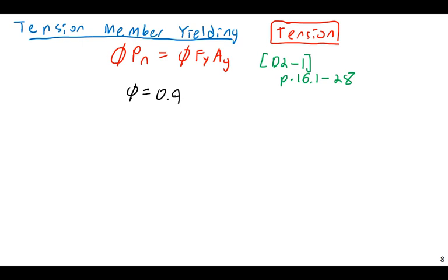It's meant to account for small but inevitable variances in the resistance that's actually present. Questions? Yes? Isn't that equation independent of the resistance factor, though? This equation here, yes, it's going to be independent of the resistance factor, although not necessarily, because at least here, phi Pn, yes, this part is, but this part isn't, because for yielding we're using the yield stress. With fracture, we're going to be using some ultimate stress as well. Okay? Other questions?